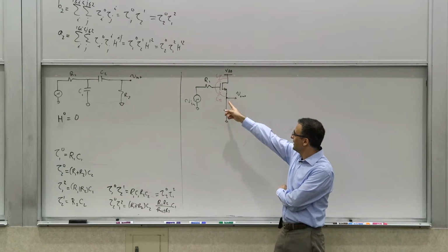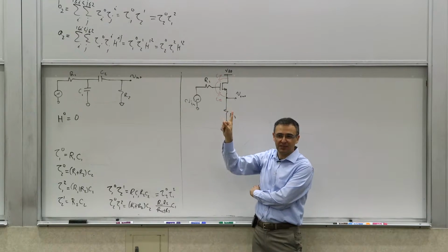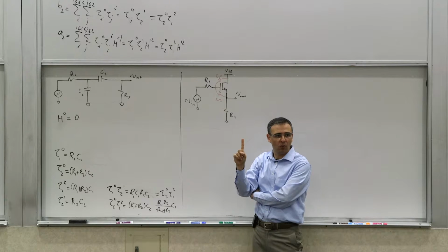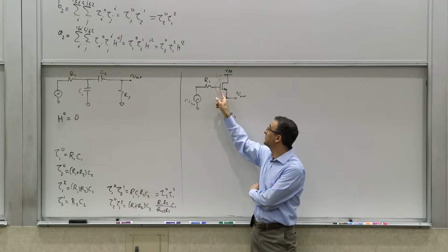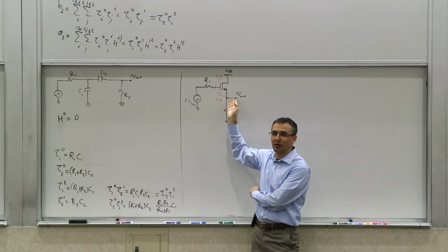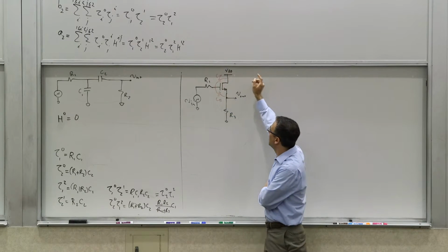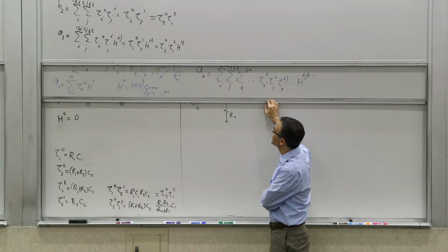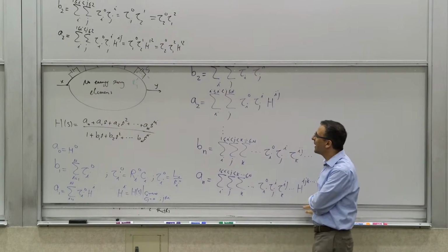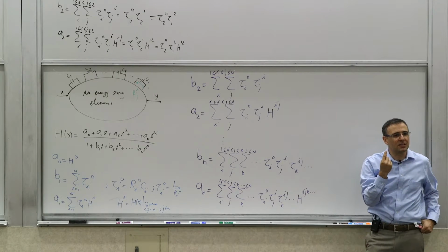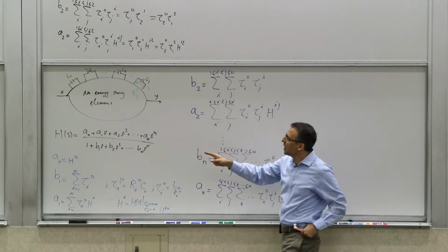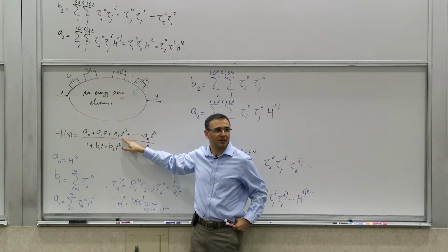Yes, right. So in this example, it's just what's the maximum number of zeros you can have? 1, right? Because you can short circuit this one and you will get some output, but if you short circuit this and that at the same time, you get nothing because you've short circuited here to ground. So where did that come from, that test? If you think about it here, look at this. Maximum number of zeros is the highest order non-zero A coefficient, right?